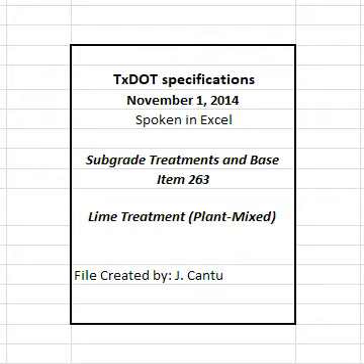5. Measurement. Lime-treated base will be measured by the cubic yard, square yard, or ton, as a composite mixture of lime, flexible base, and recycled materials. Measurement by the cubic yard in final position and by the square yard is plans quantity measurement. The quantity to be paid for is the quantity shown in the proposal unless modified by Article 9.2, plans quantity measurement. Additional measurements or calculations will be made if adjustments of quantities are required.